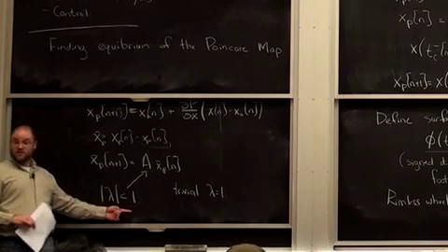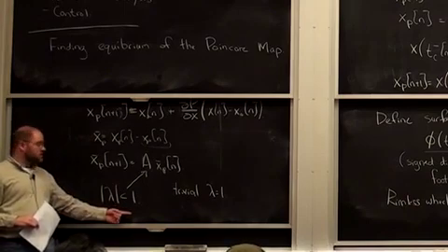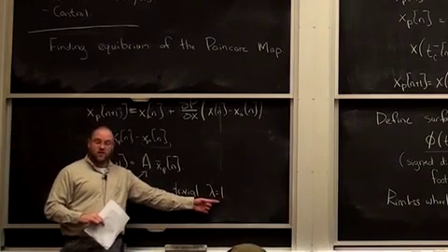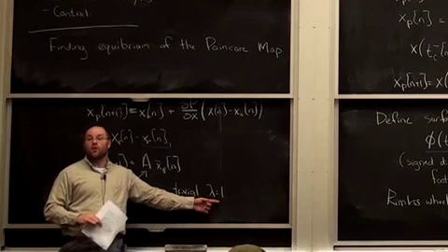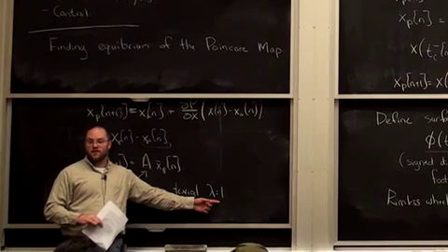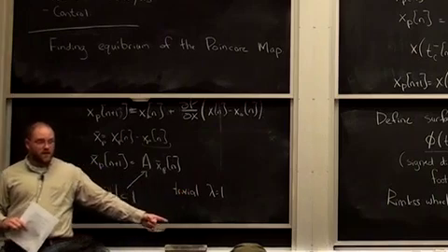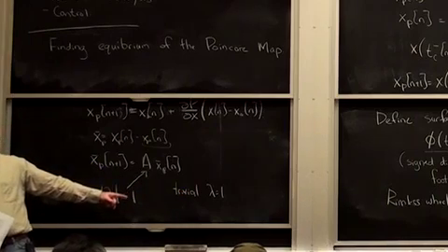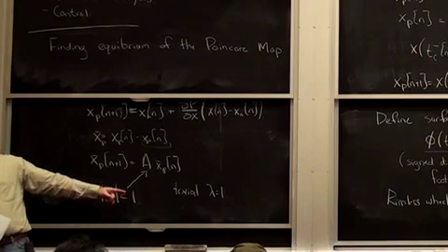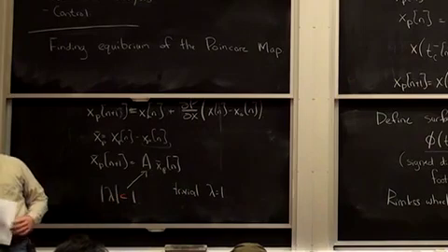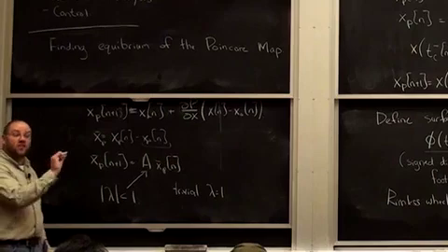This is the standard stability criterion for a discrete time system. But I notice that there's always a trivial eigenvalue that equals 1. It makes sense because it's in a loop. Do people see that? There's one direction that I can push it in which it does not reject that disturbance, and that's the direction along the limit cycle.